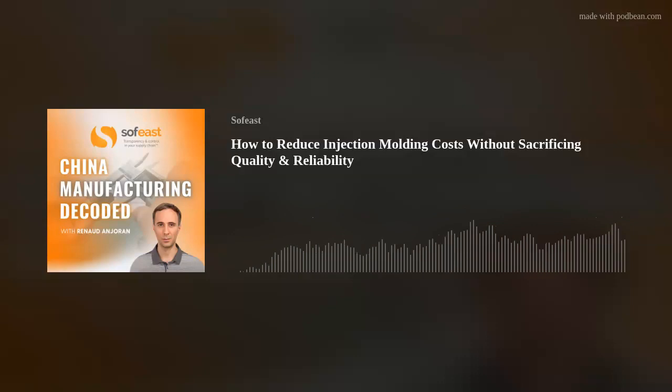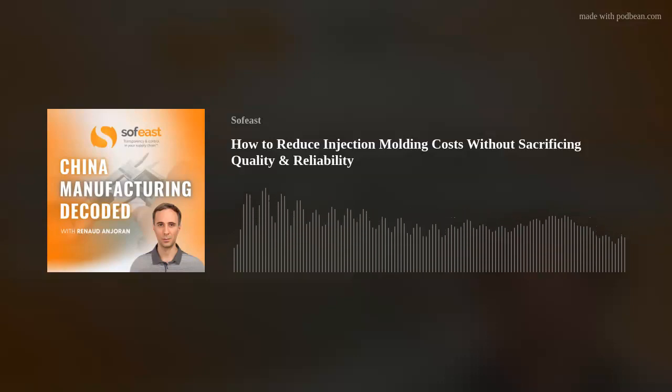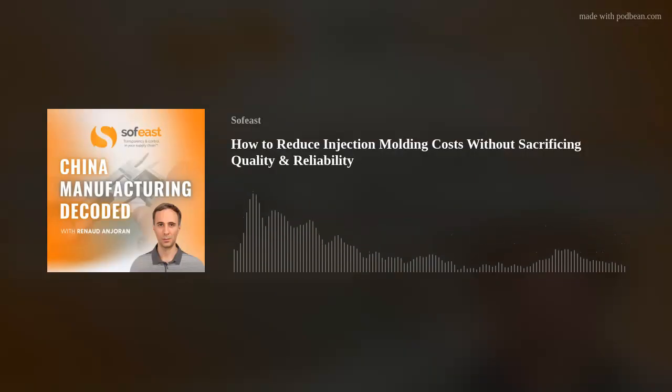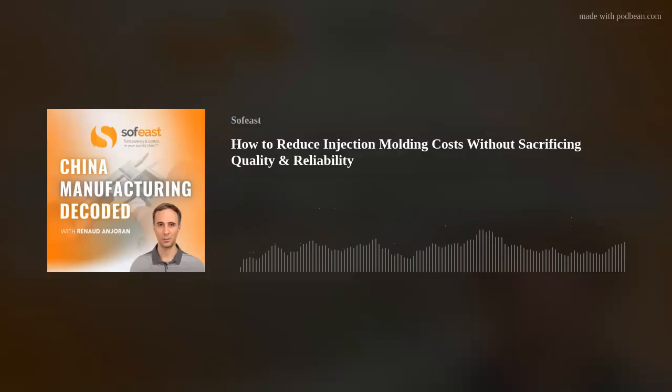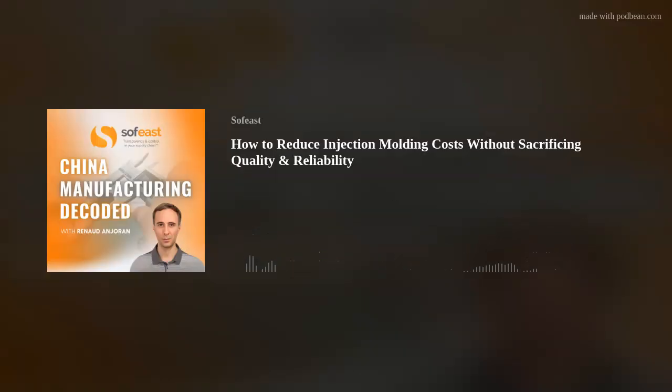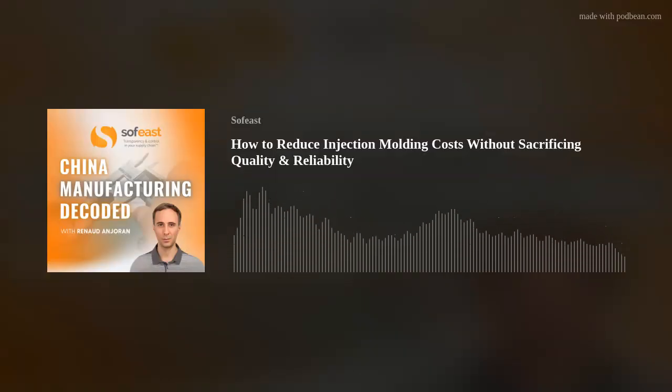Why would I say that? Simply because if it's your first product out and you're getting your business off the ground, and you do get momentum, you will need version 2. You will automatically go for that upgraded product or extended product range within your portfolio. So there's no need to run a fully hardened steel tool that's going to do 1 million plus shots. However, the cost difference between a soft tool and a hard tool is not as much as two soft tools.